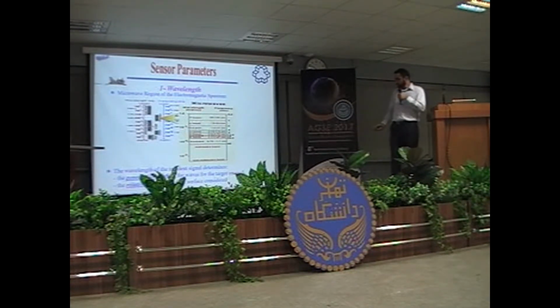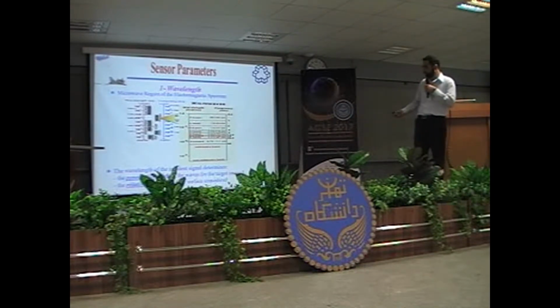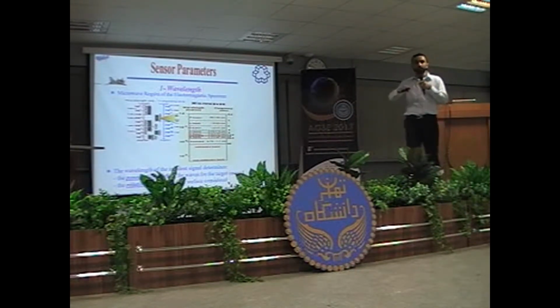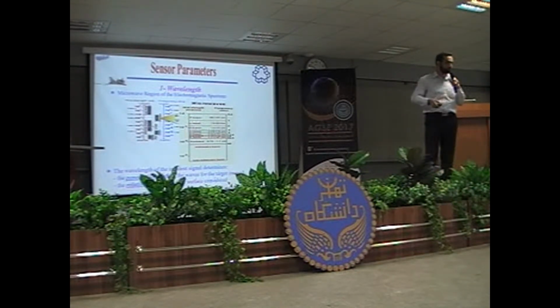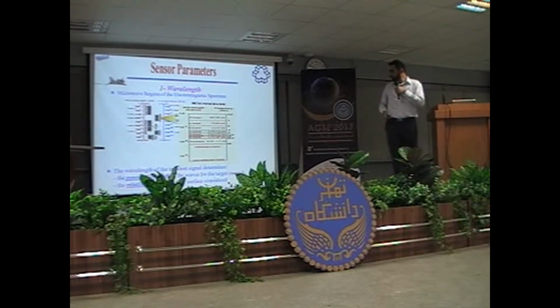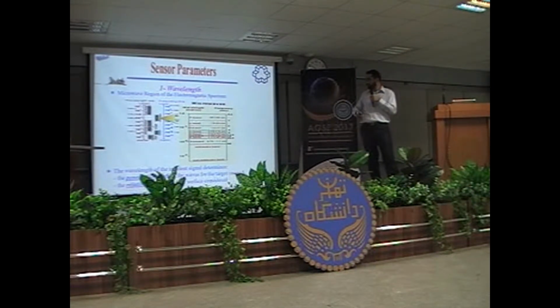And here, as I told you, the penetration depth is very dependent on the wavelengths that you are using, and also the relative roughness. I talked about the roughness previously, and I told you that roughness is not an absolute term. It depends on, let's say, the wavelengths that you are using. In one wavelength, one surface can be considered rough, and in another wavelength, it can be completely smooth.